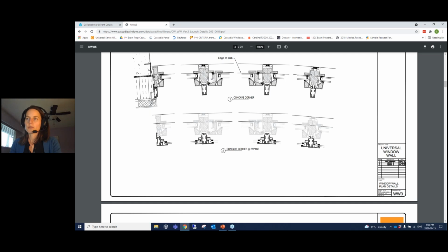So the way that the windows couple in two parts here, with an H-shaped extrusion and then two halves, it does accommodate some amount of angular alignment, I would say. And we have done a project recently that has a big concave window in Vancouver, similar to this. So I can't tell you the exact angle here, but it's gentle angles like this that can be accommodated.